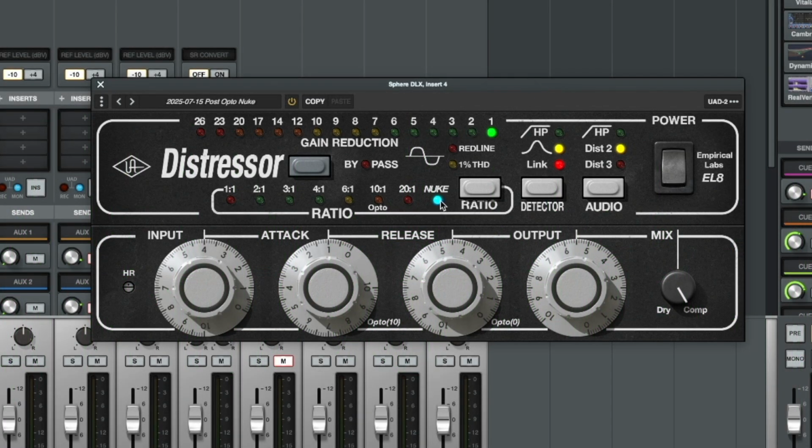It's in nuke mode, so any volume above the reduction of the previous compressor is going to kick in and limit it. And I've got this little feature enabled, which increases the gain to de-ess my audio. What it's doing is it reduces the gain of the S's more than the rest of the audio, just to keep those under control. And I've got a bit of distortion enabled just to add a bit of second harmonic distortion too, so it makes the audio sound a bit warmer.